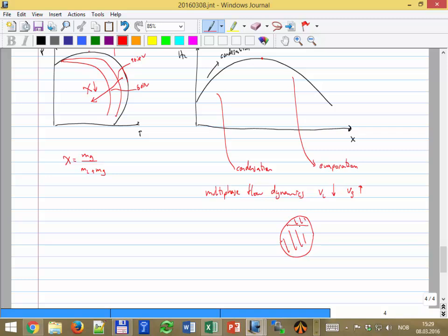But what is a bit suspicious about this case is that multiphase flow depends on many things, but it depends also on the inclination of the pipe, right? If I have the pipe going up, then the gas will tend to go quicker than the liquid. If I have the pipe going down, okay, and in this case, how is the pipe? Horizontal. So really, if I have an effect that one phase is going quicker than the other, I'm not so sure that that's the explanation. But you have to think about that also when you think about why the holdup is doing that.